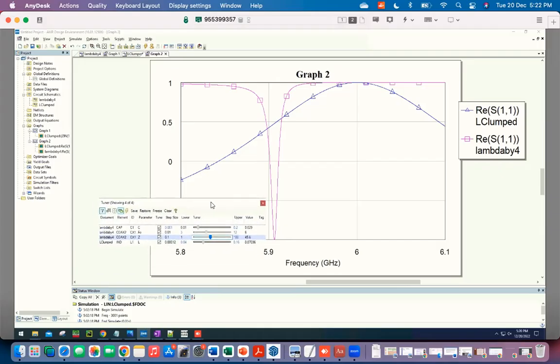So this is again something you have to keep in mind when you are designing devices. Because you design some coupling capacitor, then later on you decide to change the characteristic impedance, you have to redesign the coupling capacitor or adjust the length to get the same frequency and also to get the right Q factor. Because the Q factor will also change because the total capacitance will now be different if the Z naught is different, and the effective dissipation can change as well.